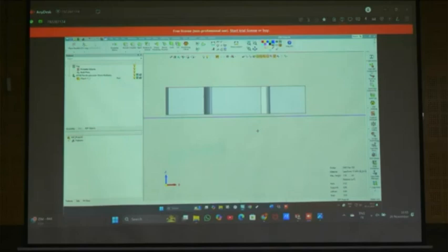And if you are adding a support in SLM, the support structure parameters are different, and the heat accumulation will be more. We can get a good print if we are applying a support, be it a solid body or anything. We can apply the support, but here I kept a body of 1 mm. The recommended value is 0.3 mm to go for the wire cut EDM. 0.3 mm is enough. Just to apply some different supports I just kept this. So I will open the support manager.